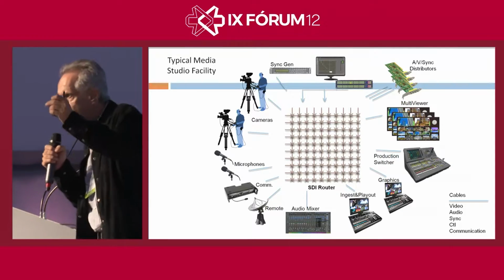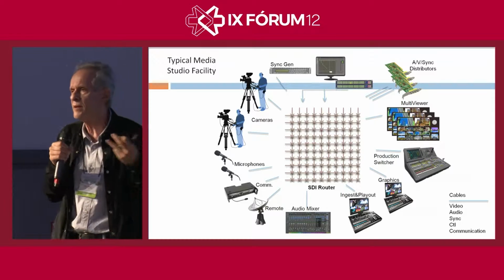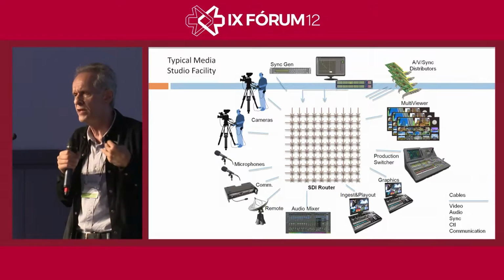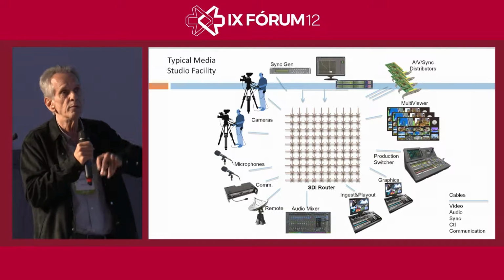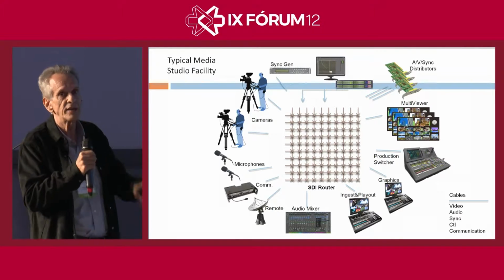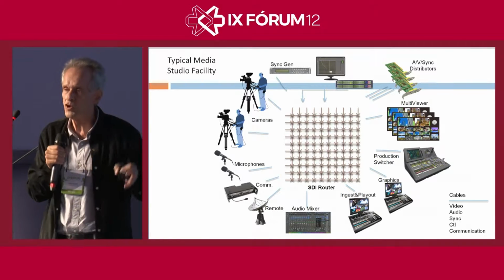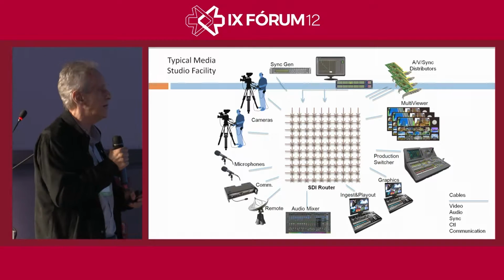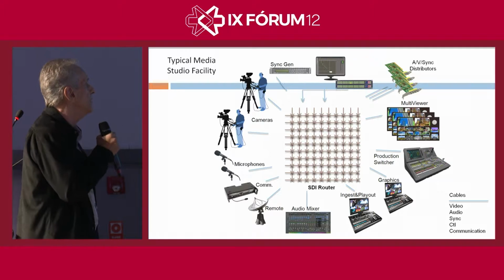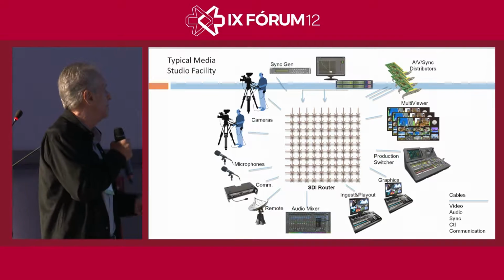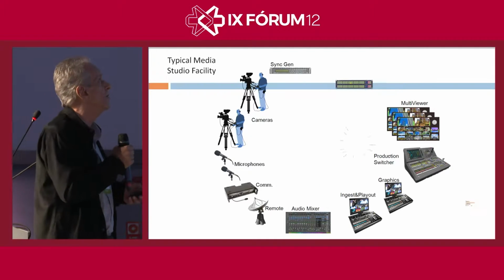Every source should start with the same pixel, the same point, the same line, so that we can work in unison to have special effects amongst the different sources. And everything in the SDI world is interconnected through an SDI matrix that would be cross points, in charge of the interconnection between the source and the destination. So basically, this is the type of installation that we have in the SDI world.